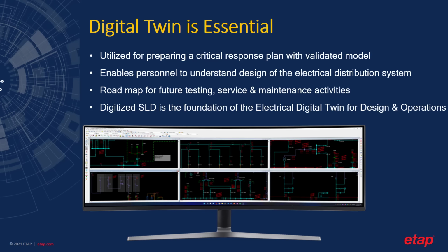activities. An intelligent electrical digital single-line diagram is a digital single line that includes advanced functionality and awareness of the device's characteristics and behavior. It dwarfs simple graphics by being able to adapt to the connection changes, unlike a conventional drawing. A digitized SLD is the foundation of the electrical digital twin that can be leveraged not only to communicate the network connectivity and asset information, but also as the basis for power system analysis from design to operation.